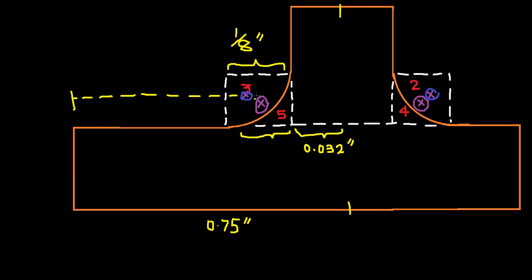So what do we do to find that out? Well, there is a specific formula for finding the centroid of a quarter circle, as we discussed back in the first part. Now, what was it? It was 4r over 3 pi. This 4r over 3 pi is precisely what this length is. By finding out what 4r over 3 pi is, just by substituting 1 over 8 into this formula, we will get this missing length.